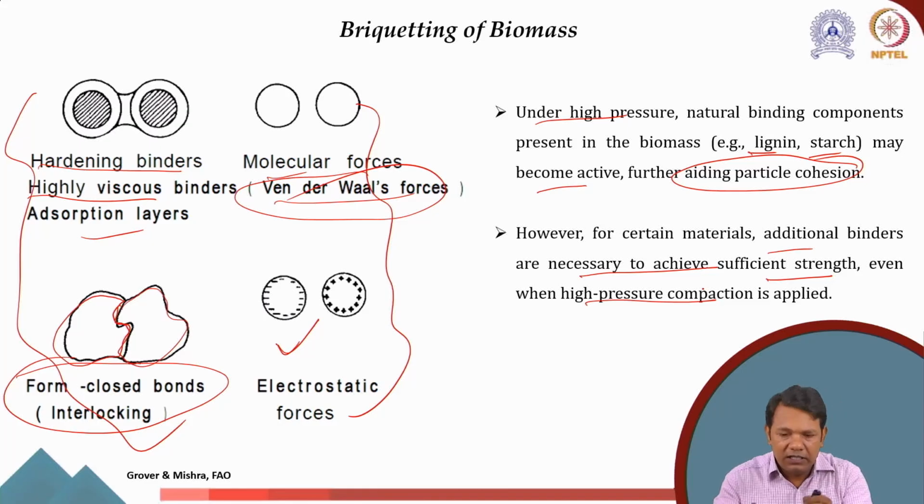So as I said, in most cases for high pressure you don't require a binder. That's a thumb rule, but it's not a law. That means in most cases, let's say 90% of cases, you will not require a binder, but there will be 10% of cases where you will require the addition of a binder even in high pressure compaction.